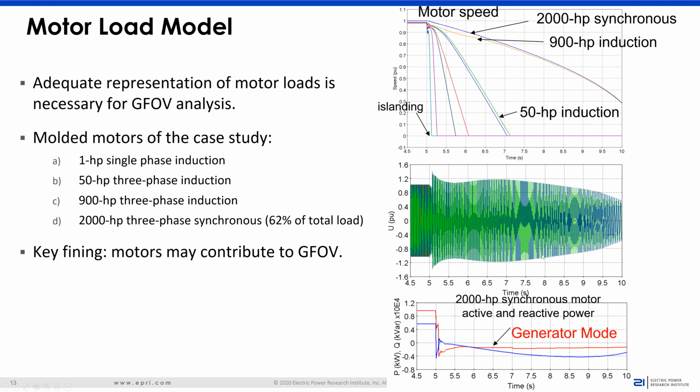And because of these nonlinearities, if there is a small difference in characteristic, it could be a large difference in conductive current and energy consumption of the arrestor. So that's why it's best to consult with the arrestor manufacturer for specific curve data. And this curve also depends on the service experience of the arrestor, the batch in which the arrestor was made. Essentially, even arrestors of the same model and manufacturer can have different VI curves.